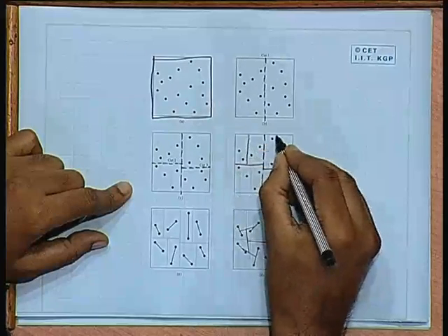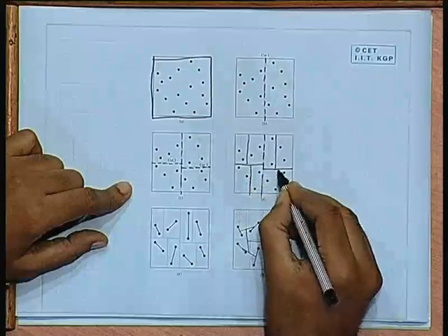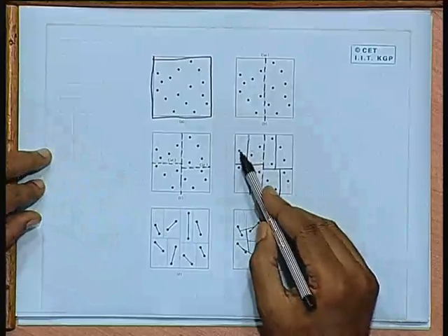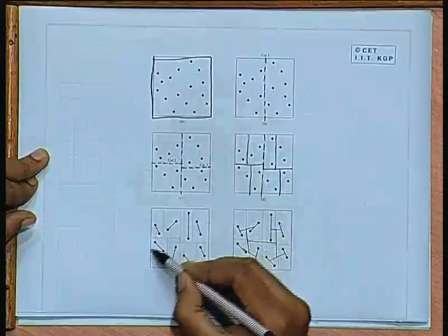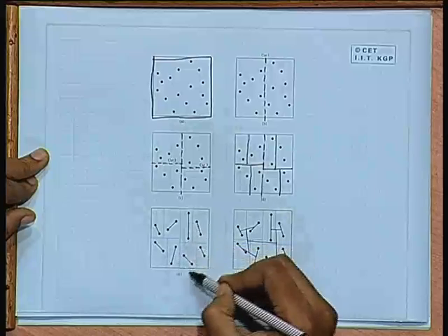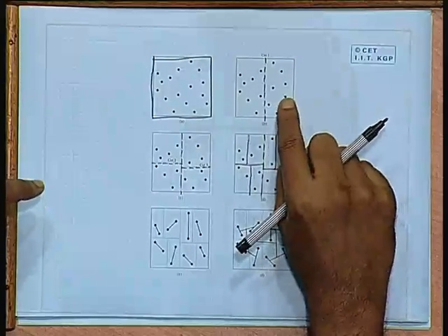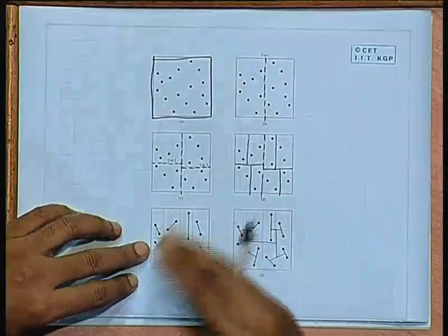Now, with a vertical partition. So, now we have a situation where in each partition the number of clock pins is 2. So, you can directly connect them in each partition with a line. Now, the center of mass that I was talking about, you can backtrack from this one and go on computing the center of mass and complete the tree.